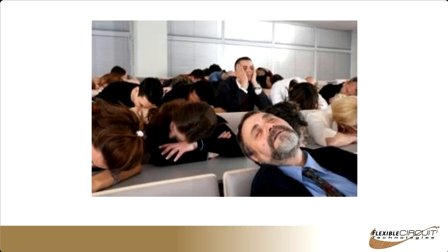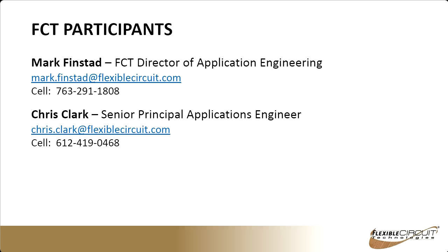Okay. How are flexible heaters typically powered and controlled? So as Mark had described in that previous slide, the most common thing is where we have 4 lead wires coming off. 2 are for the NTC or thermistor, and 2 are actually powering the circuit hooked up to your power supply. And as Mark had mentioned, we want to make sure that we know what that voltage is going in so we can design the heater appropriately.